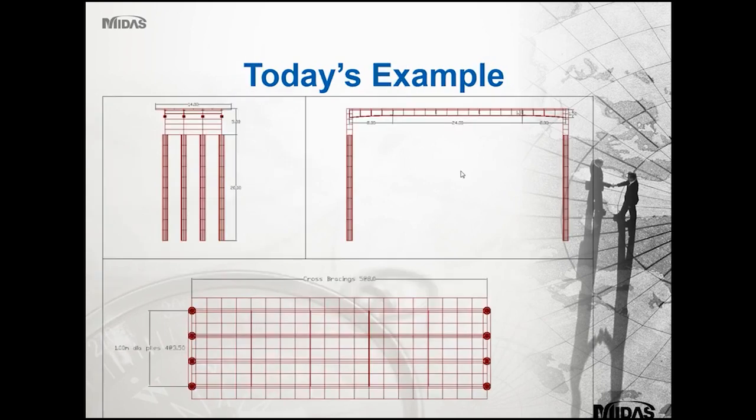So as you can see, it is a 40-metre single span integral bridge. It is 14 metres in width. We have abutments which are 5 metres in depth and piles which were 1 metre in diameter and 20 metres long. The depth of the abutment is 1 metre, and for this example we've also set the piles at 1 metre as well. We also have a tapered section at the left hand end of the bridge and also the right hand end of the bridge.